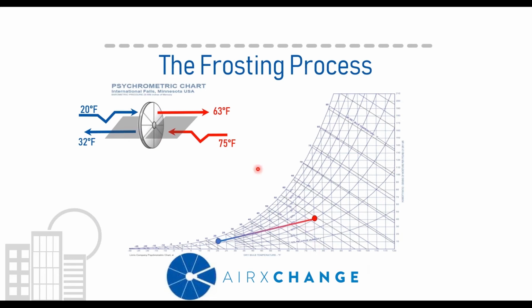Now, this particular process, as you see up here, has resulted in 2 leaving conditions. The supply air is at 63 degrees, and the leaving exhaust air is 32 degrees. If you remember when I said that you needed liquid water to form frost, in order to condense water on the heat exchanger, these points have to become saturated. All the moisture exchange for this process so far has been done in the vapor phase. Neither airstream has approached the saturation curve.